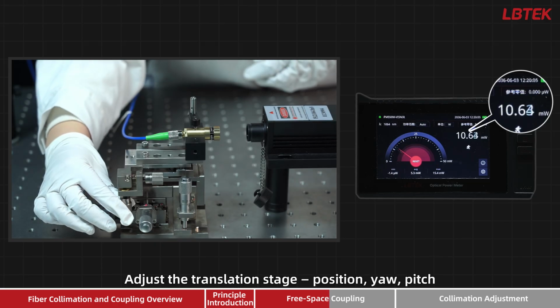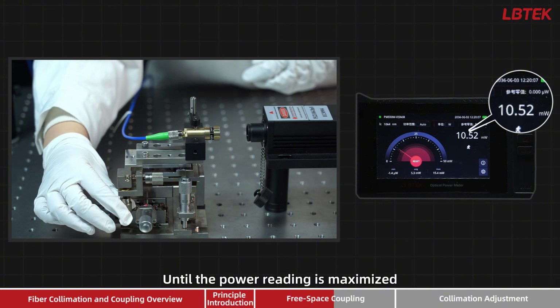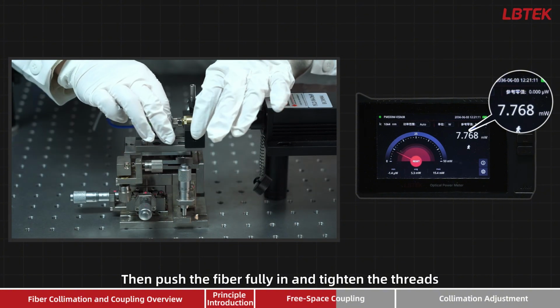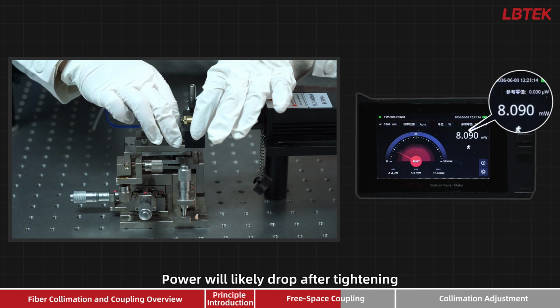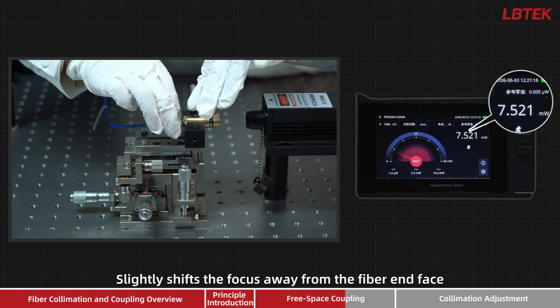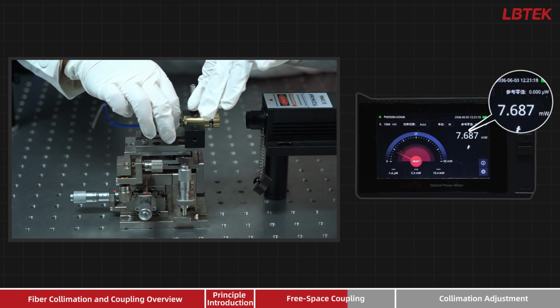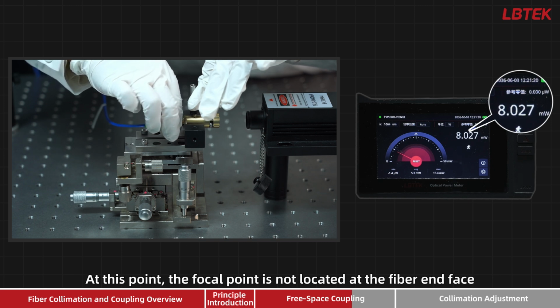Adjust the translation stage, position, yaw, pitch, until the power reading is maximized. Then, push the fiber fully in and tighten the threads. Power will likely drop after tightening. That's normal because the mechanical stress slightly shifts the focus away from the fiber end face. At this point, the focal point is not located at the fiber end face.